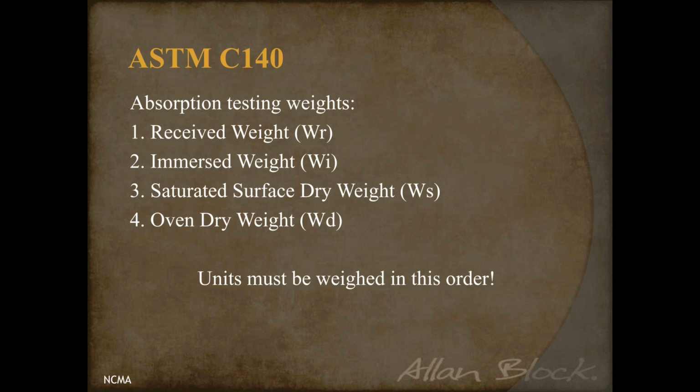Okay, and I am not a testing guy. I do not do testing very often. I have seen it done, but the ASTM C140 will give you more of the equations on how exactly they do this, but they do make it very specific on when a block is to be weighed. And you weigh it when it comes in.